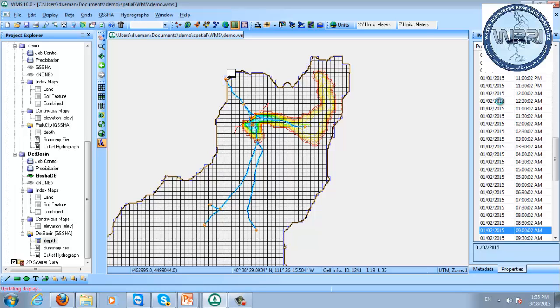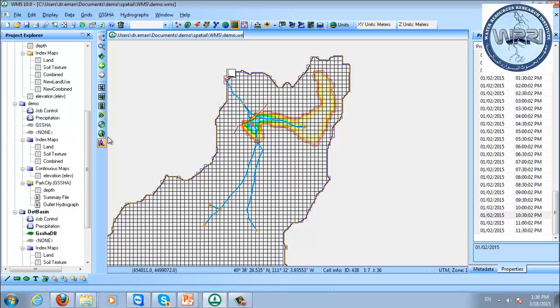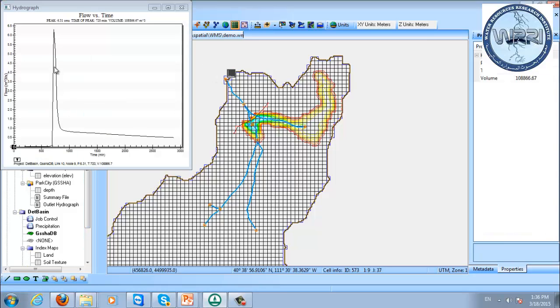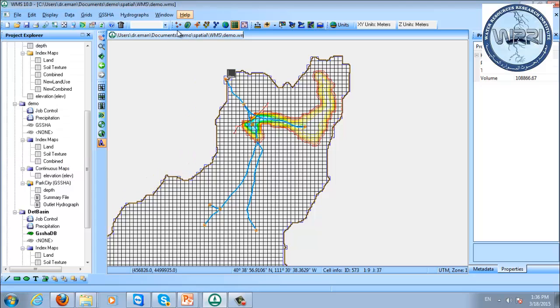And I don't really get any rainfall until kind of later in the simulation. And actually you're probably not going to see the contours from the rainfall because most of the depth, the deepest part, is where this lake is located. There are different options too. So for scenario modeling, here's my hydrograph at the outlet. This hydrograph is a lot lower than the hydrograph without the detention basin.